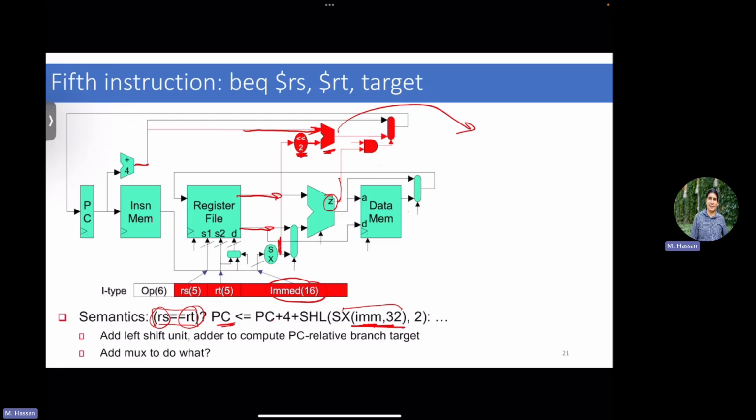And because this can be a very simple ALU only for addition, remember that in Amdahl's law, in our performance lecture, we said we make the common case fast. How many times do we need to add an offset to something, right? If you have any branch, you should do this. If you also have jumps, sometimes you might need to do this. If you have jumps like function calls, you also need to do this.